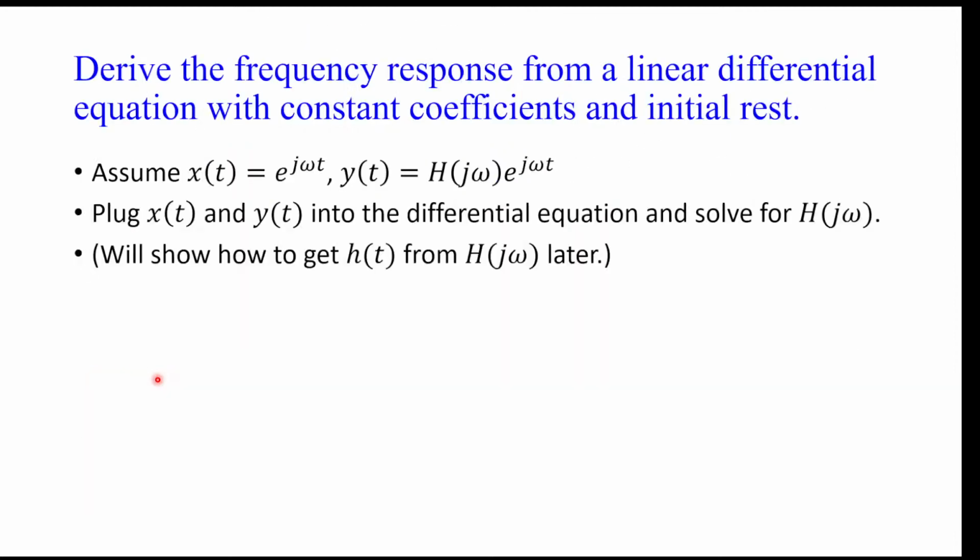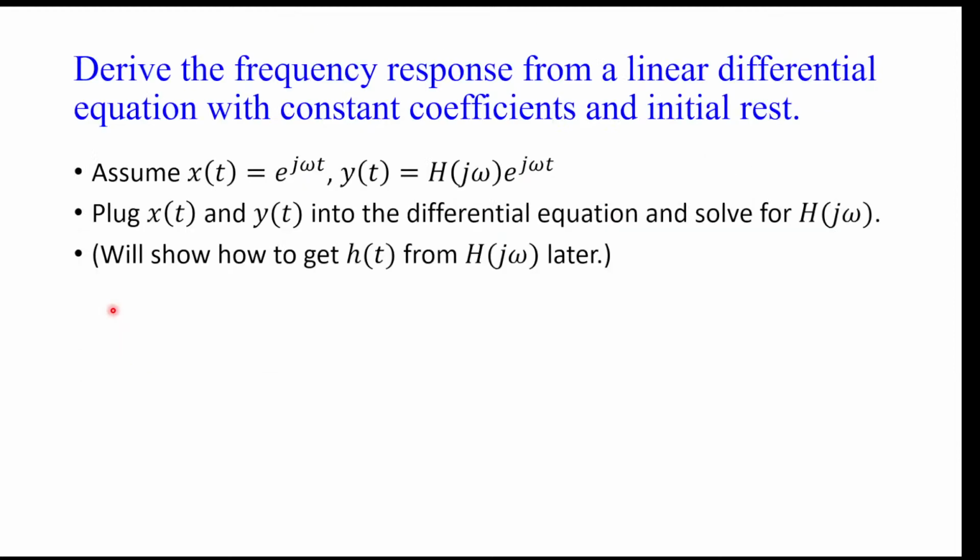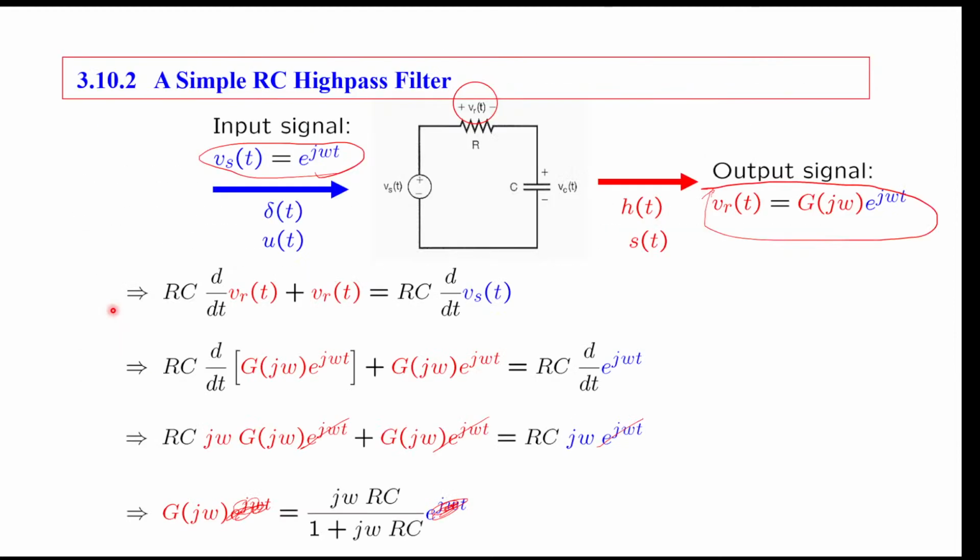But let's get back to filters. So that was a bit of a digression to differential equations. So, back to filters. We saw how to construct a low-pass filter from this RC circuit, and how do we construct a high-pass filter? A high-pass filter uses the same circuit, but we just change our output direction. So the same circuit, but now we say, what if we output from the voltage between these resistors? Then we write down the physics with this equation, and we do the same thing.